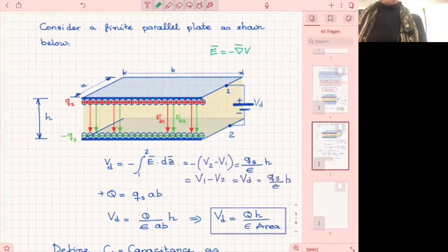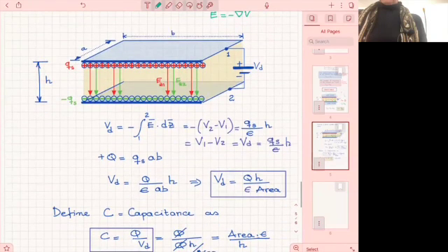Because of that relationship, we took the integral from 1 to 2, which means that instead of having potential, I took the difference between the two values of the potential, between 1 and 2, which gives us voltage, all right? The integral of the gradient of the potential between 2 points gives us voltage. It's like one potential minus the other. If we therefore apply this from 1 to 2, that gives me the voltage I apply, which is V sub D.